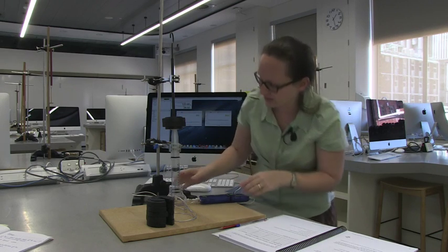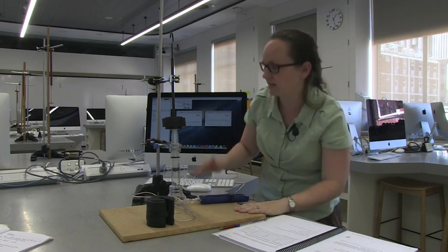Now, with this experiment, it's really important that everything is carefully aligned vertically. We don't want these masses applying any sideways force onto the syringe. We want everything vertically up and down. And again, this clamp at the top is not actually to hold these masses, it's just to provide some stability and stop them falling off. So this is just resting on the top there so that the entire 1.5 kilograms is applying a weight force downwards. So just make sure that everything is nicely aligned vertically.